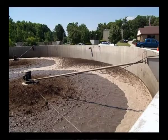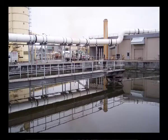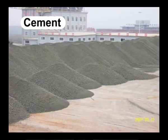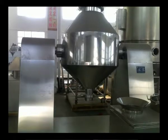In contrast to the latter example, high water content may be expected, thus requiring a completely different approach and technologies. One possibility is sludge co-firing after drying. One suitable process is cement and burned lime production, where an alternate fuel can be fed using a special feeder directly into the rotary kiln. In some cases, however, it is necessary to apply special sludge incineration technology. This is very often based on a multiple hearth combustion chamber.